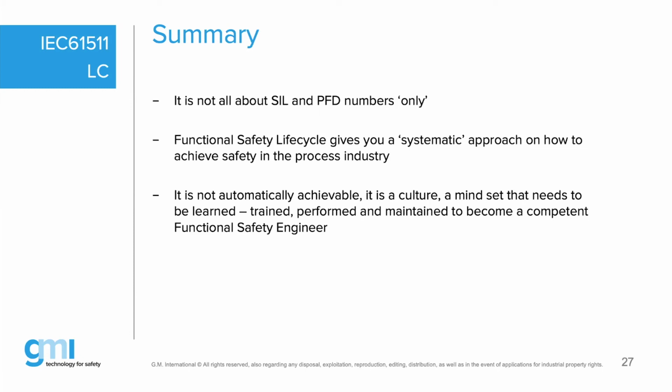And I can tell you one thing, even when you have a SIL 1 or a SIL 2 or a SIL 3 safety PLC, it will not make your safety project SIL 3 compatible. That means one of your elements may have compatibility to a certain SIL, but it stops there. It doesn't go through your entire safety loop function. And it always comes down to competency. That means you need to be trained, or maybe you can do some self-education.